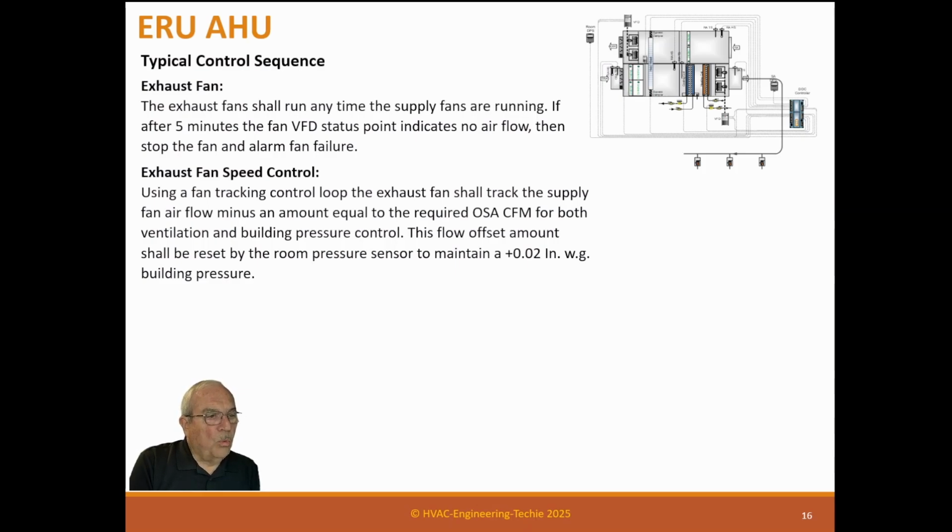It could be 0.015, which is really low, but it could be more. I wouldn't make it above 0.03. What happens if you get 0.03, 0.05, you can actually start interfering with door closers, pushing doors open, so we don't want to do that. 0.02 is a really sweet spot for that.